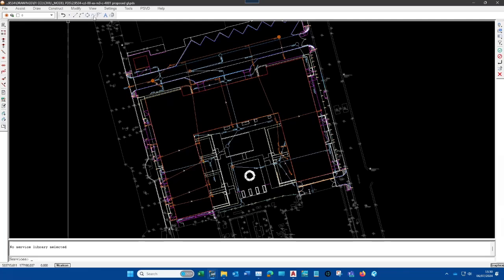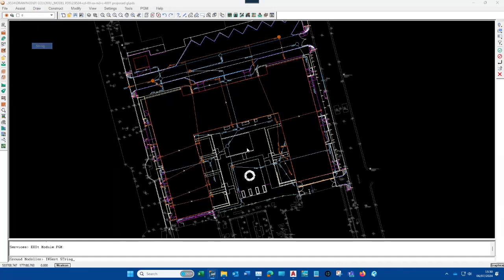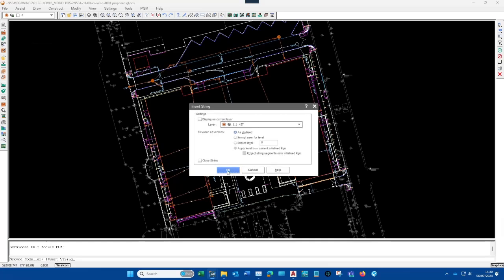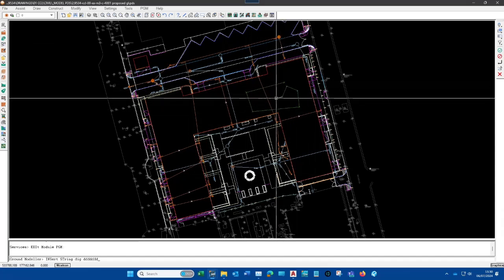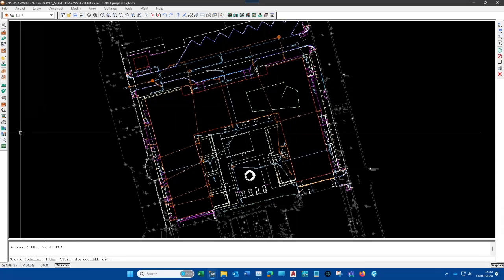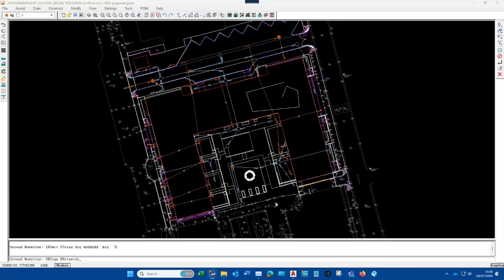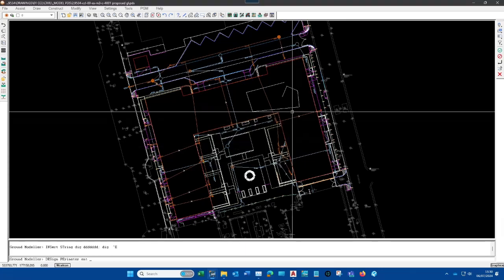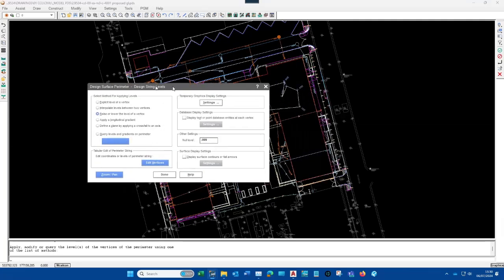So for example, if we go back to ground modeling really quickly, if I go draw string, I choose this layer. If I go 1, 2, 3, 4, 5, 6, enter. If I go use this surface design perimeter, modify existing, click on this, yes, close it temporarily, move this.